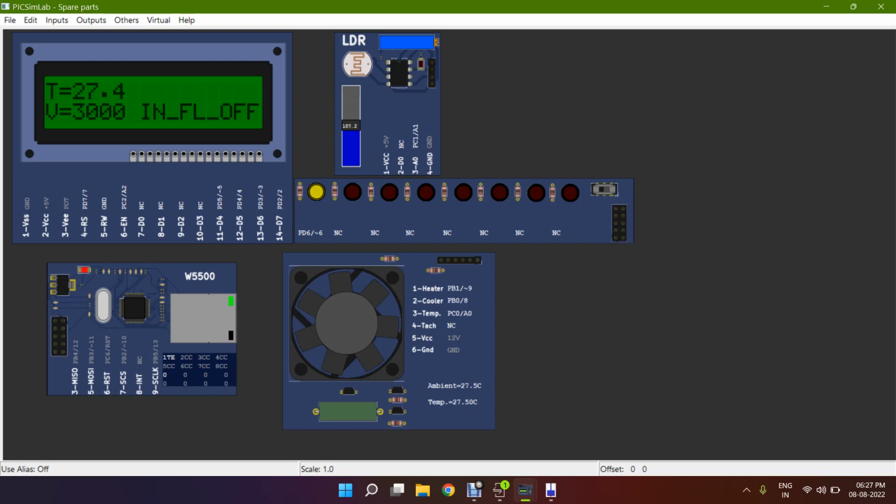Now I bring it down. I'm simulating the day. So from night it's transitioning into day, and we see that the brightness of the light is decreasing successively and switched off. So this is essentially an application of pulse width modulation, as we discussed in the slides before.